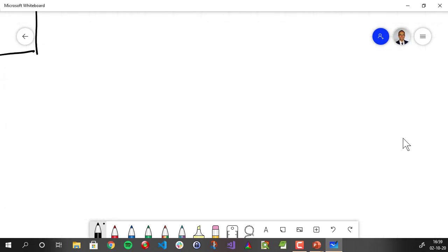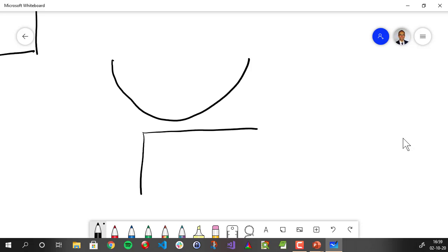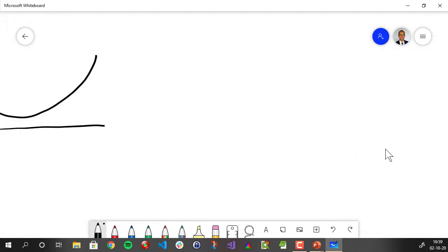So, okay. If you have a tool like this, and then some mesh that can go into contact with this tool, you must understand how contact works, but you haven't had the lecture about contact yet. So how does it work? You have a tool, you have a mesh, and the method is called the penalty method.